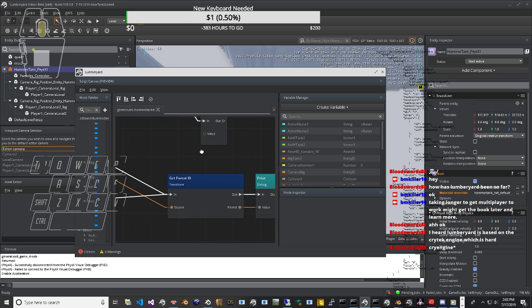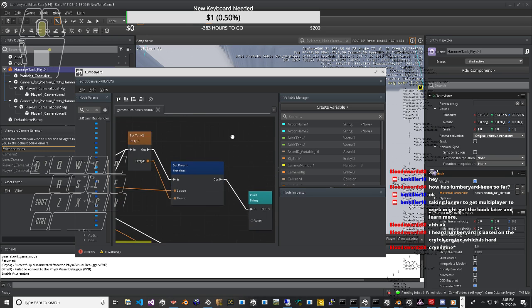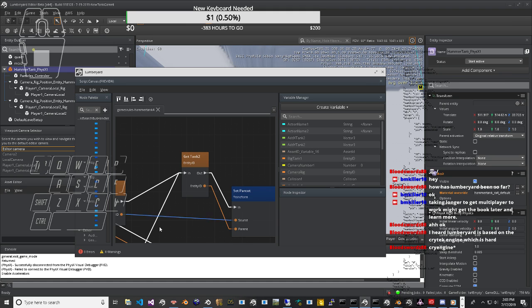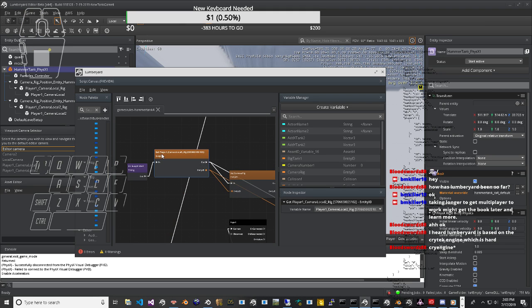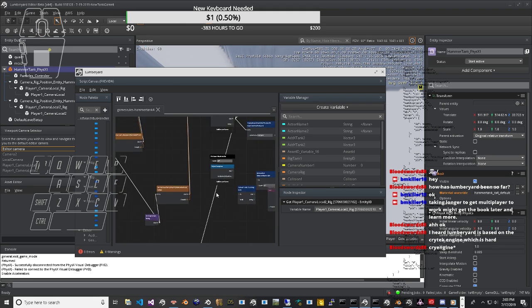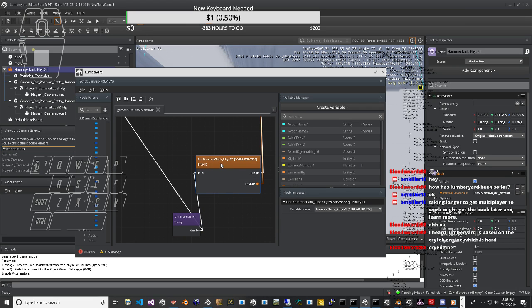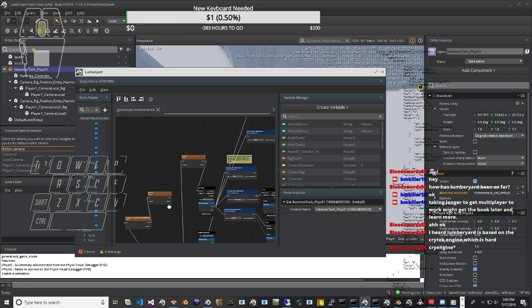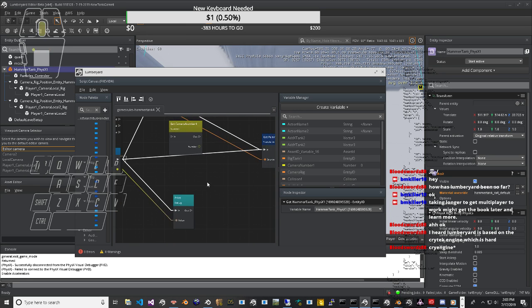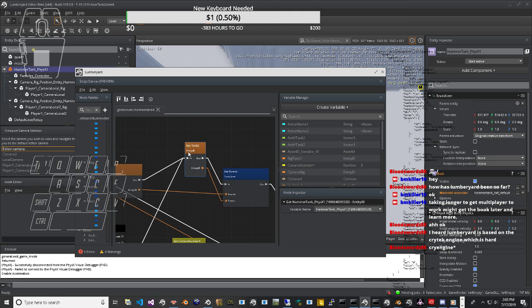However, despite fierce trade secrecy, industry and academia have reached apparent consensus in recent years on a formula that summarizes experimental and theoretical data. This so-called magic formula is not a solution to equations of motion. A solution in such a form is not feasible. It's just a convenient fitting of commonplace mathematical functions to data. It allows one to compute forces at a higher precision than something like RARS, see parts 16 and 19 of the Physics of Racing, PHOR, but without integrating equations. Therefore, forces can be computed within a reasonable time, say in a real-time simulation program.